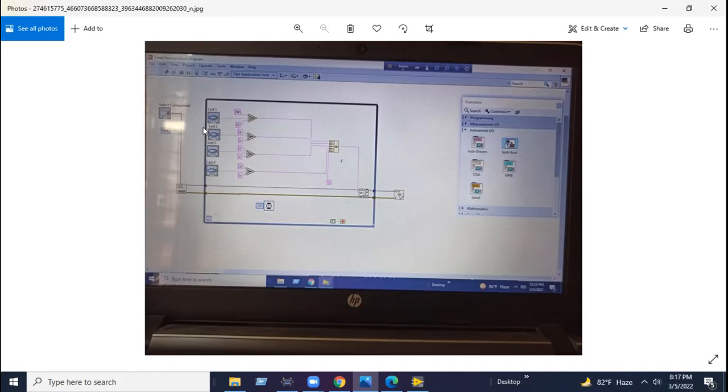After ending this command, to pass this data, we have put a select component here, where this COM port has a default baud rate, which is 9600. This whole system and circuit would run inside a while loop. This is our while loop, and we have set the time to 250 milliseconds, which means this while loop will be repeated after 250 milliseconds.